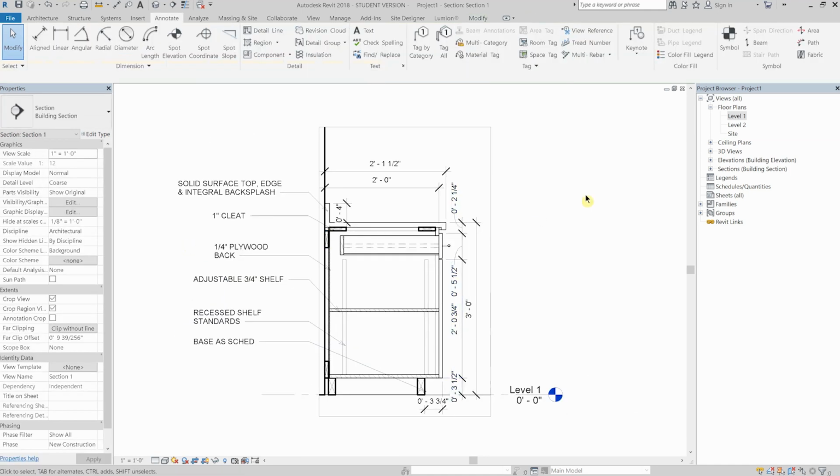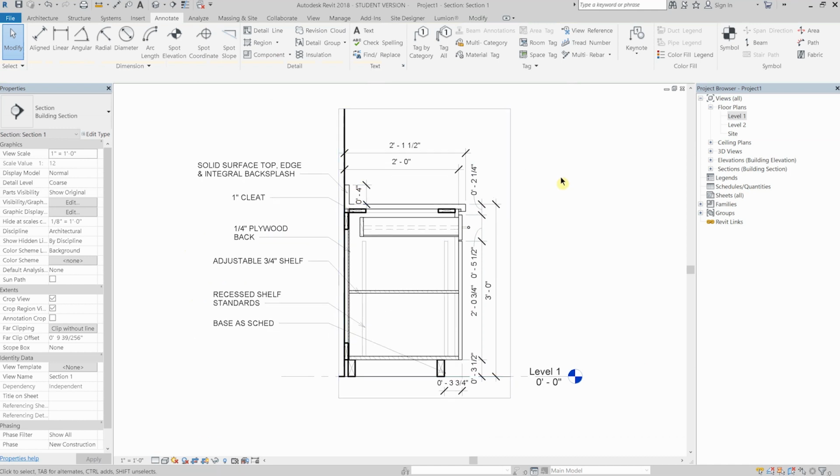And as you can see, I'm going to leave it here. A simple section, not too many elements. This is the same workflow you're going to use when you're doing any detailing on walls, for example, as well as roof, ceiling, or flooring types. You're always going to use dimensions, text this way, as well as the detail lines, regions, and the components.